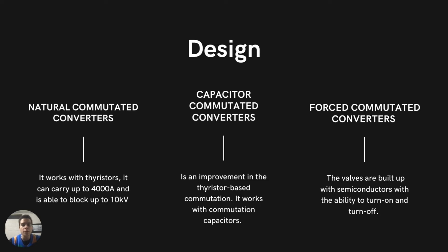For the capacitor commutated converters, these converters are characterized mainly by the use of commutation capacitors that are inserted in series between the converter transformers and the thyristor valve that we were talking about, and they improve the commutation failure performance of the converters when connected to weak networks.